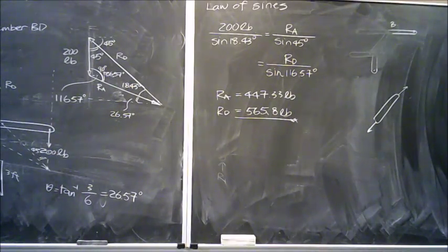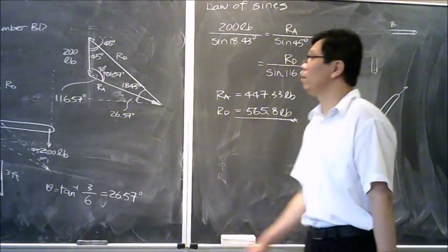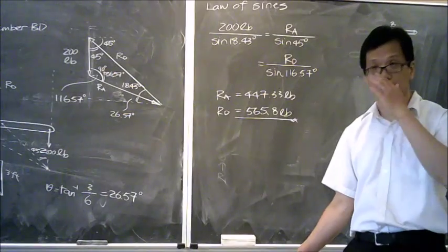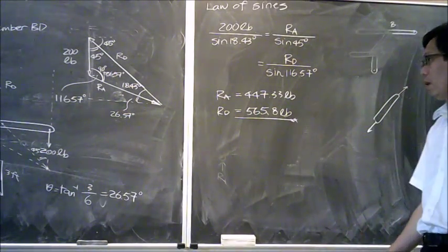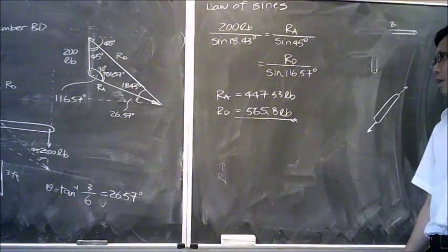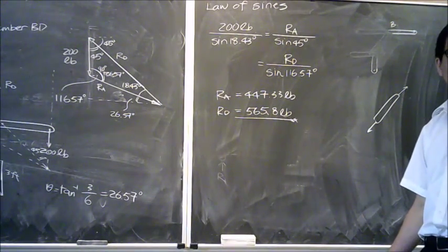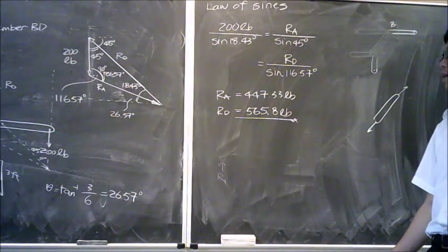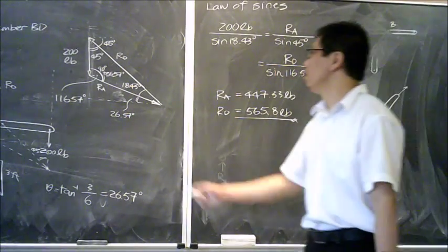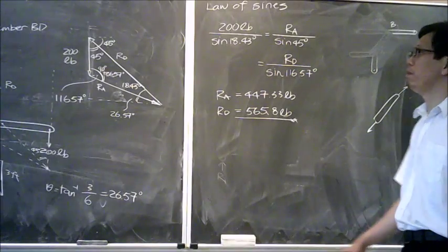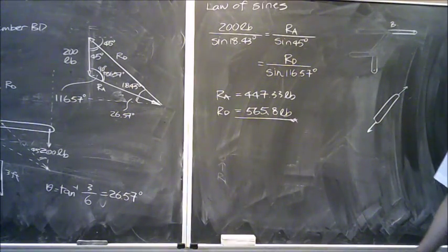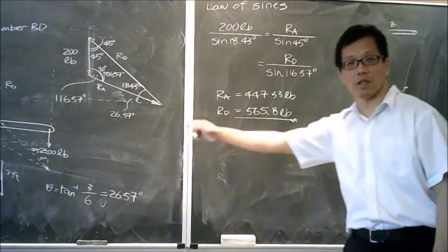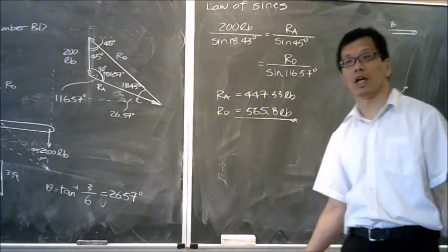Is that clear? So sometimes you might say, okay, this is not so convenient to me. I would like to use XY configuration. That's fine, because personally I prefer it that way. But sometimes you would feel that if you decouple everything into fx and fy, it might be a little bit tedious, and chances are you might set up the configuration wrongly. So the geometry method or three-force body method is easier for you to figure out what the forces are applied to a specific location. Then you can use the skill I'm showing here to get all the numbers.